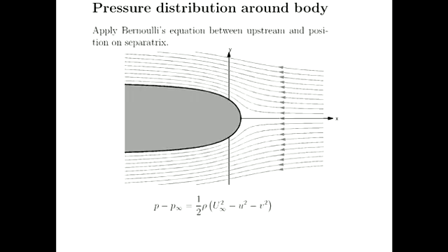Do you remember, have you come across the pressure coefficient in previous courses? No. A very resolute no. You've come across the lift and drag coefficients in previous courses, and you've definitely come across a drag coefficient. So they're ratios of some force to an inertial force, okay? The pressure coefficient is very similar to a lift or drag or skin friction coefficient. It's a ratio of a pressure force to an inertial force, okay?